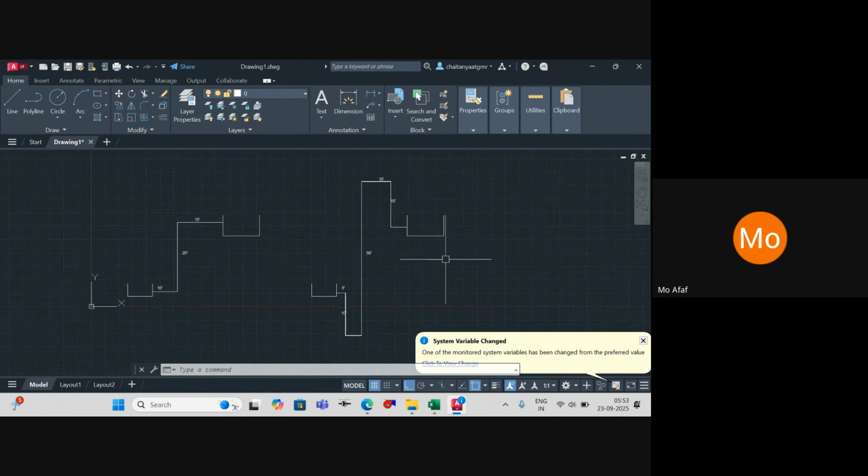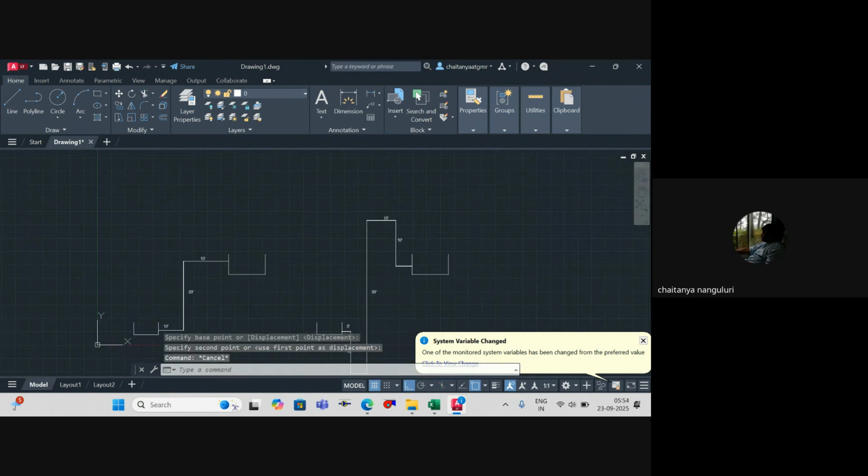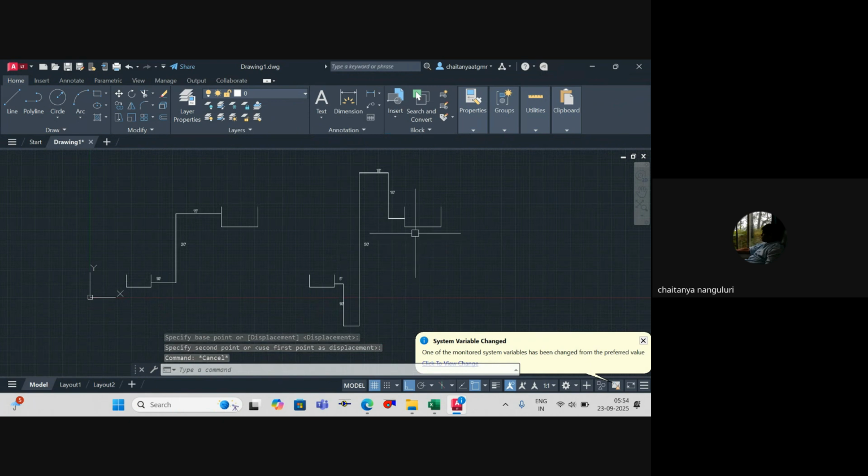It's 40 plus. That is 10 or what? Which one? This one? Yes, this 10 feet is considered. So we have to calculate till this overhead tank level, right? No, you shouldn't consider it only till the overhead tank. The reason is, unless in this circuit you lift the water till this point, will it be able to reach the overhead tank?